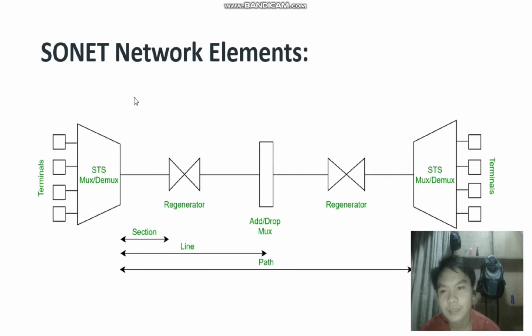So first, the STS mux or demux. What is STS? STS is a synchronous transport signal. The STS mux multiplexes the input signal in the terminal. It multiplexes the signal by means of converting electrical to optical signal. Then, after the STS mux, it goes to the regenerator.